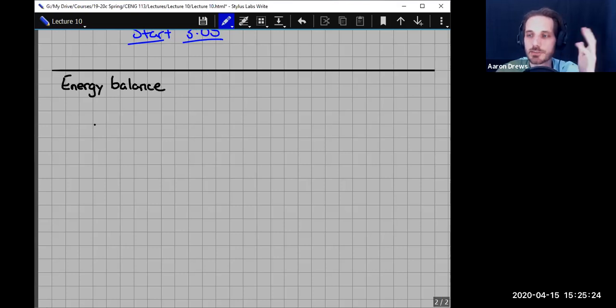Generally speaking, the energy balance that we have seen previously usually simplified down to what we call an enthalpy balance. We didn't often work in internal energy in flow systems because most of the time in flow systems, it was more convenient to define this parameter of enthalpy as U plus PV, which should look pretty similar to what you would have seen in thermo as well as 100. It just so happens that that PV term popped up all over the place, so it was convenient to define enthalpy that way.